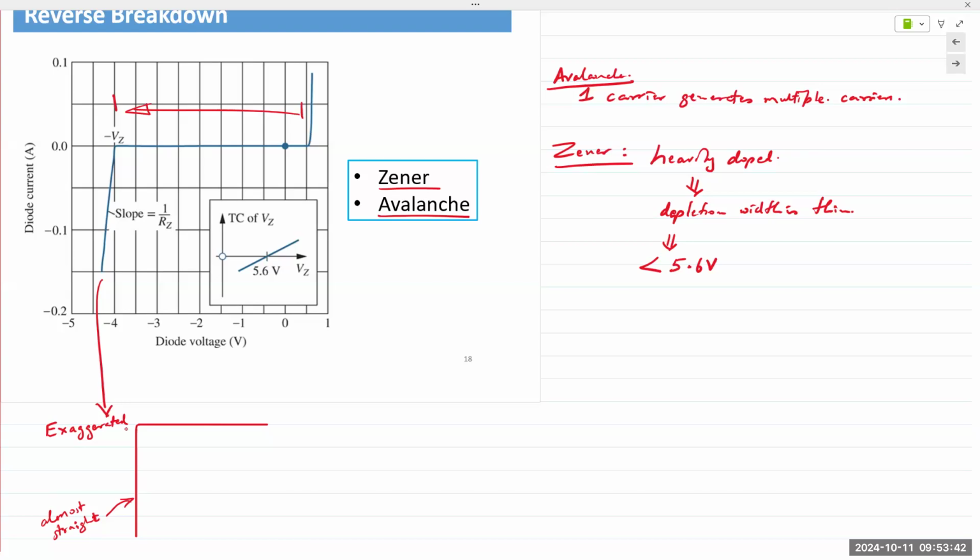Going on a little bit of a tangent, your lab kit has a set of 4 diodes, small black epoxy cylinders with gray bands on them. The gray band indicates the cathode. They are from the 1N4000 series. So you have 1N4001, 1N4002, 3, 4, 5, 6, 7. The 1 through 7 is the exact same diode. In the forward bias, it works exactly the same. The only difference is that as the number of the diode increases, it reflects the peak reverse voltage or peak inverse voltage that the diode can withstand.